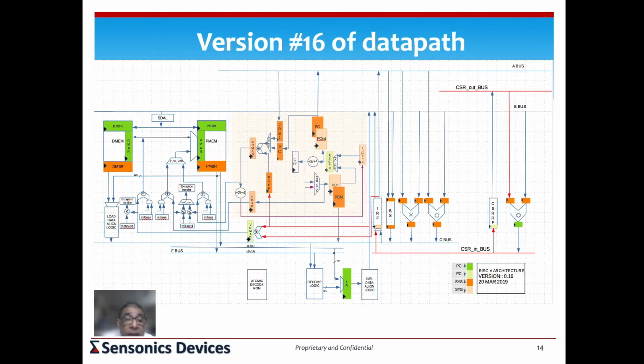So you have that. Then there is the central piece, which is an implicit piece, which again we have to infer when we write the flowcharts and so on, which is that as an instruction is fetched, you have to increment the address, you've got a PC increment, and when there is a jump, a different kind of thing happens. If you get a 16-bit instruction, there's a different kind of increment that will have to be done, and so on. Or when the instruction memory is 64 wide, you have to do it slightly differently. So all those functions are inside another piece of logic. We can call it the PC incremental logic. That's the central piece, which is highlighted in peach.